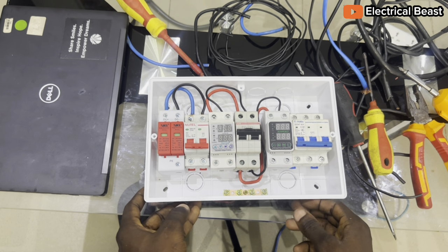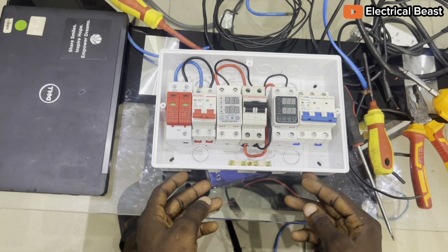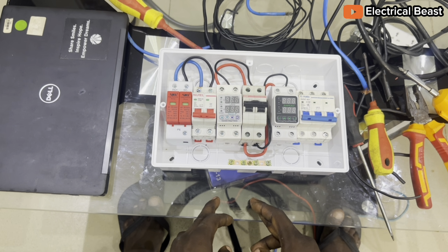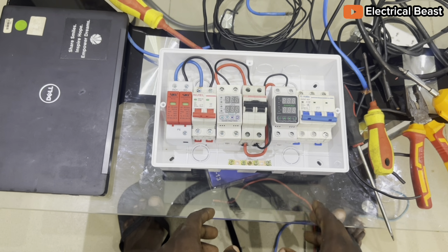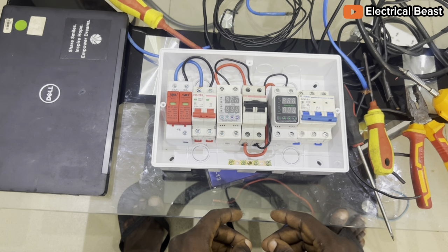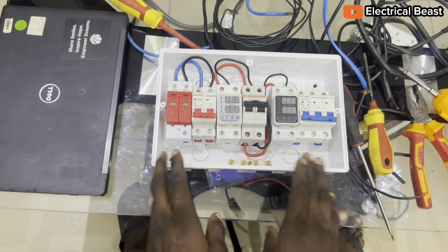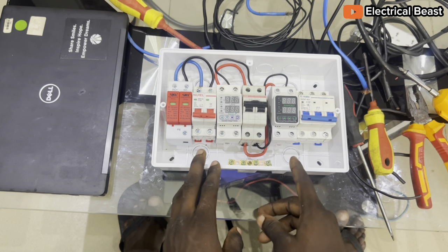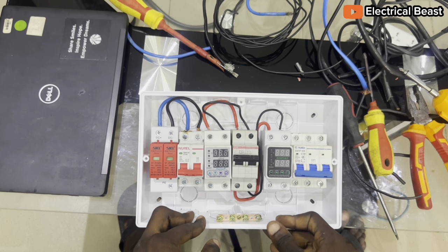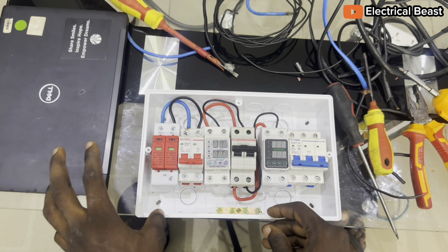Okay, and again, then we have the battery breaker. It's just straightforward. From the inverter to the battery, you connect the breaker. Use a different box for that. You cannot put that battery breaker in this box. These are the only breakers that can fit into this box. When the breakers are too many, you can decide to split it. Get an AC breaker box or get this.